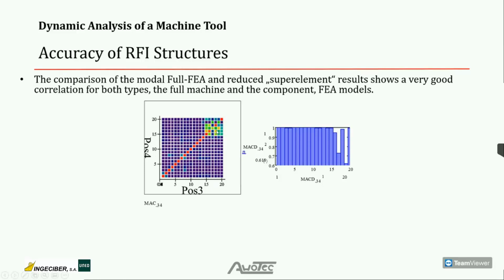As you remember, on the pictures shown before from the modal analysis, there were the higher modes from approximately 200 Hertz. There are the vibration effects of the stiffener panels of the mainframe, and they're all in a similar frequency range, but of course the eigenvectors are different, and therefore you see such a big deviation here in that region.